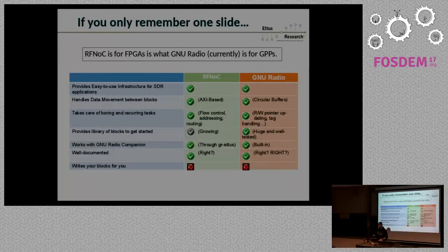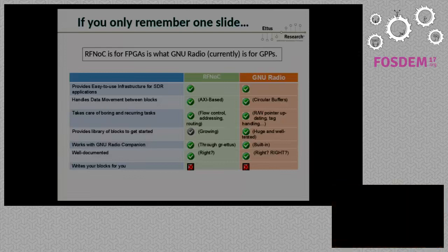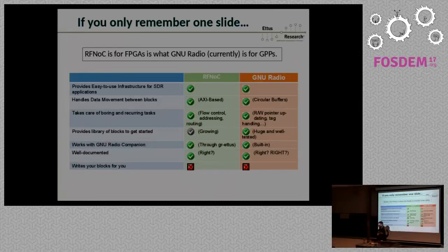What is RFNoC? It is for FPGAs what GNU Radio is for GPPs. We have this block-based modular design approach, both in RFNoC and GNU Radio. And as Marcus showed earlier in GNU Radio, we have the ability to write blocks, and then data will magically go from one block to the next. It's obviously not magic, but we don't have to care how it happens. The same thing is true for FPGAs. And what I talked about earlier, the digital magic that you have to do, is much reduced if you use a framework such as this.